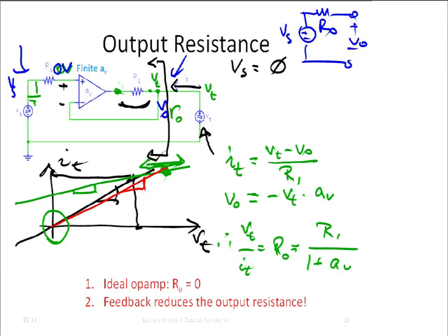but then it has a high offset voltage. What is the offset voltage? We never talked about it, but I always say that the difference between the two inputs of an operational amplifier should be zero if you have high gain feedback. It's actually not true. A small voltage appears that, depending on the op-amp, is anywhere from a few microvolts to a few millivolts. In some applications it really doesn't matter. In most applications that we deal with in the lab here in EE40, it just plain doesn't matter. That's why they tell you about it.